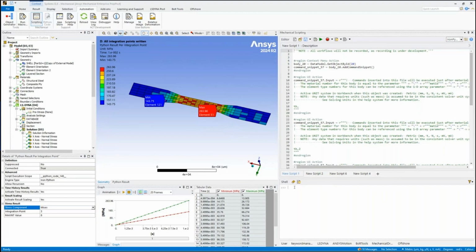We can start off down in the console. Any commands that we put in here, we can interact in real time with Ansys Mechanical. So you can see I've used this ExtAPI, which is effectively an external API command, but really useful. If I then use the Python object dot notation to get to the object, you can see I get an autocomplete, a code suggestion of all the functions underneath that object.